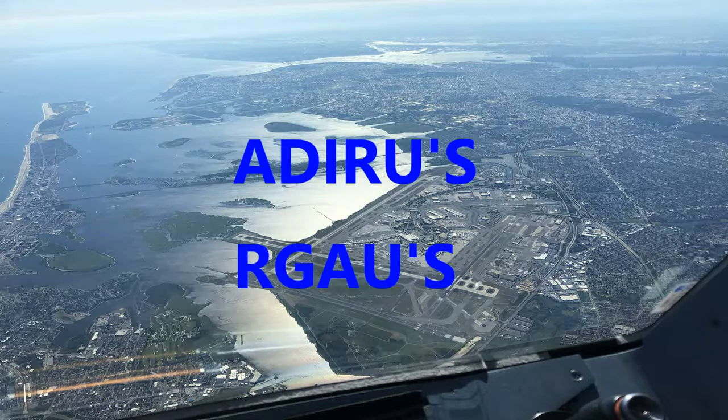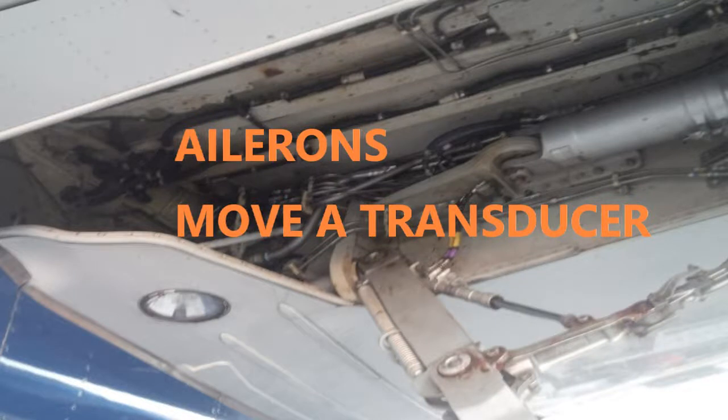What's happening technically with the ailerons when their job is to do the roll for the airplane? Well, the ailerons are moving a position transducer so that it can give surface position feedback to the computers, through, obviously, remember I said that translator, your flight control remote module, or your electronic module. And that's how that's working. It's using transducers.